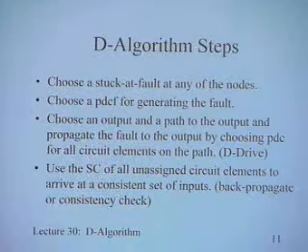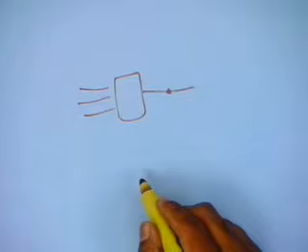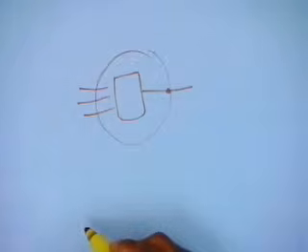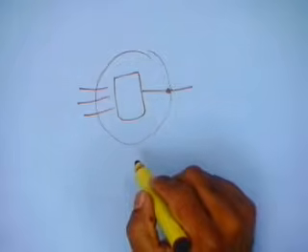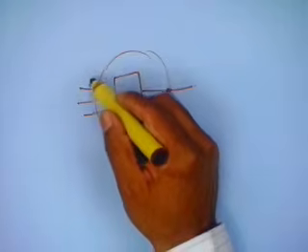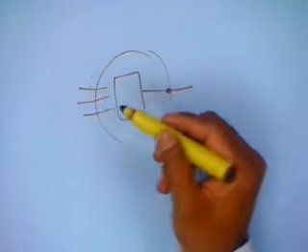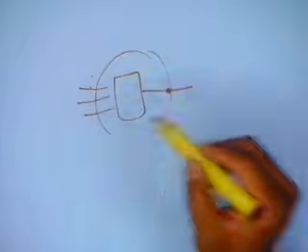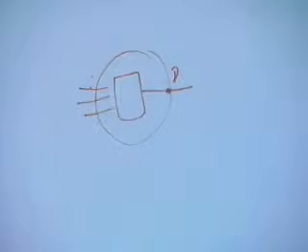So for this particular fault, there is some element and I have chosen a stuck at 0 fault here. It may have 2, 3, any number of inputs. So I will choose a PDCF of this particular gate so that I get a fault over here. What this will do is specify something at the input. Some of them may be don't care also, but some specifications will be there at the input and there will be a D at the output.